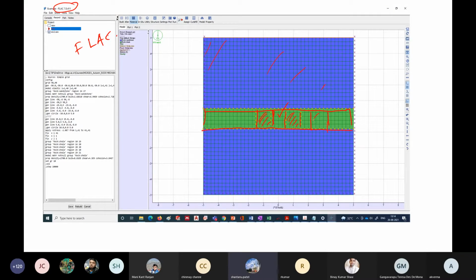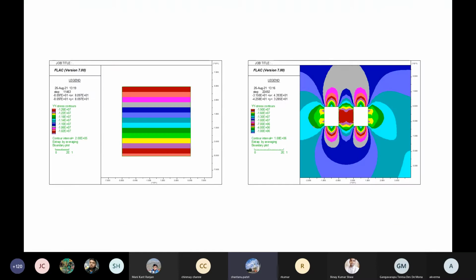So when I'm doing this, let's say this figure here shows how the stress condition is changing inside the material, inside the ground, right? So our potash deposit was somewhere here, okay, and we are trying to take it out by making some excavation, and we are trying to leave some pillar here, right? You can see the stress values, how much is coming to this. Before the excavation it is around 11 MPa here.